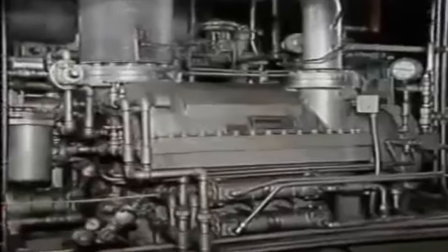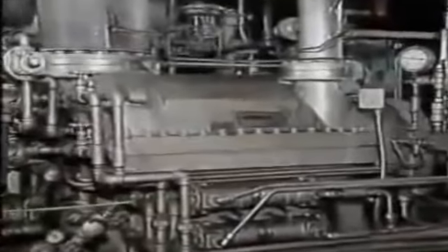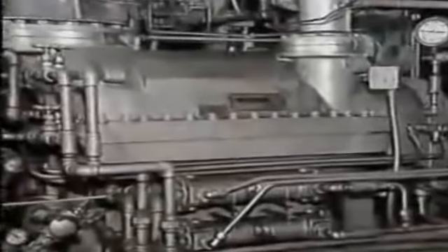As a general rule, it's important not to exceed the ramp rate while a compressor is being brought up to speed. However, in many centrifugal and axial compressors, certain rotational speeds, called critical speeds, cause severe vibration. This vibration is caused by the physical characteristics of the compressor's rotating parts.